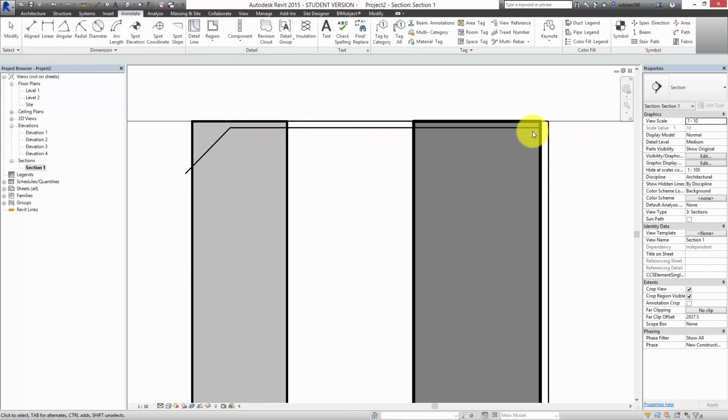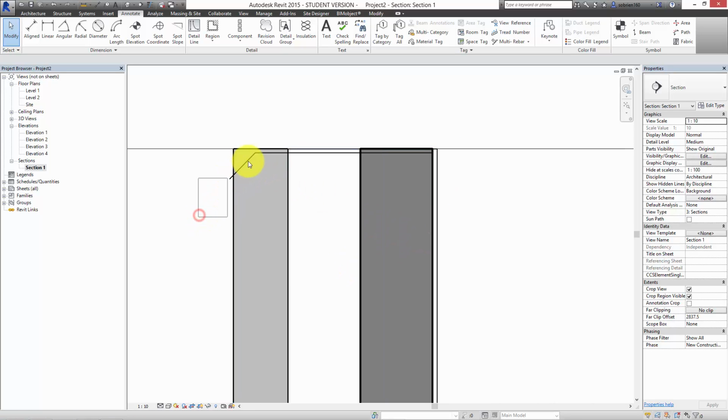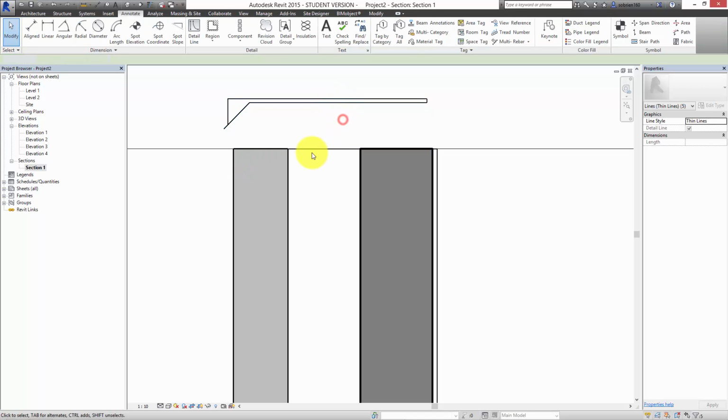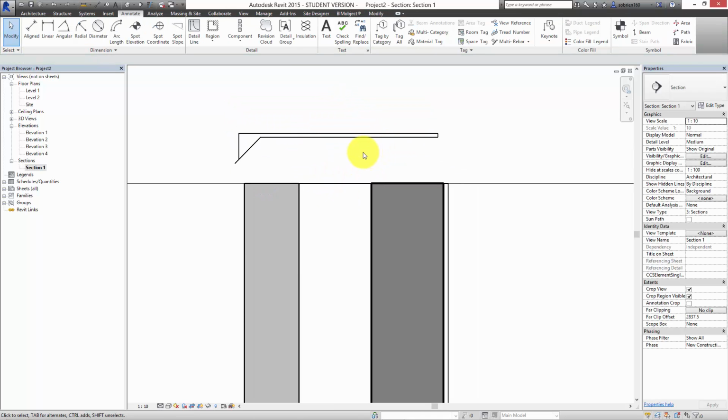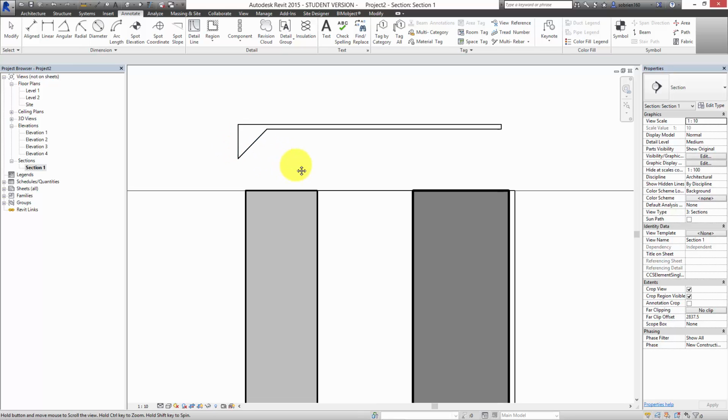I'm not including the gypsum wallboard in the tolerance because we want that to be finished on the inside, so it doesn't really concern us. So I'm just going to leave that like that for the moment. So if I then run the window around it, we could take this out, and we have an idea that this is the cutout we want to take from the wall in order to make the tolerances and in order to make the chamfer at the edge here. So I'm just going to trim the edge here so it's nice and clean.